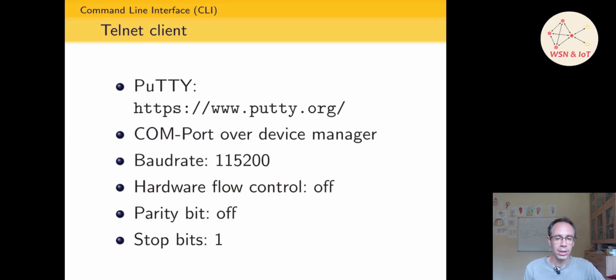After transferring the firmware, the Thread network is already started, but for communicating with our devices we need a terminal program. I'm using PuTTY here now. You can download it from putty.org. It's a quite simple telnet client. You can of course also use HTerm or whatever.